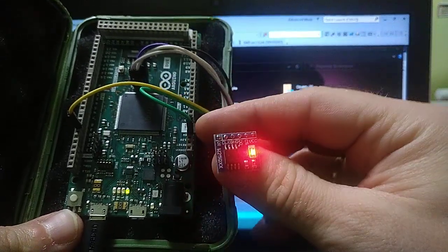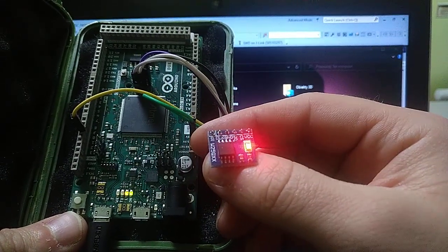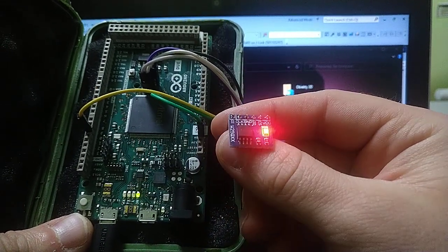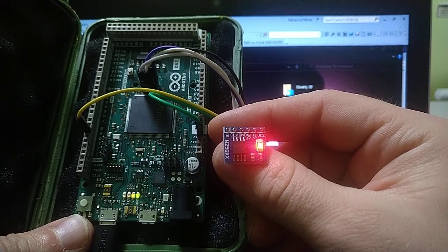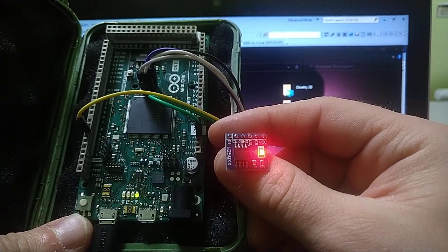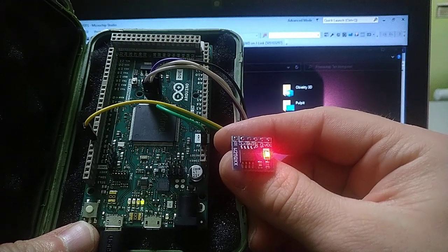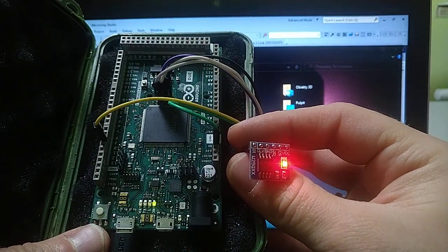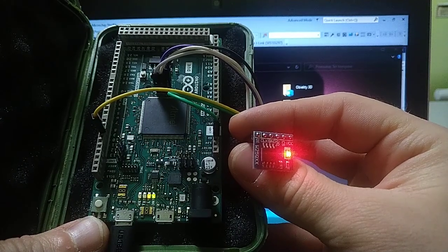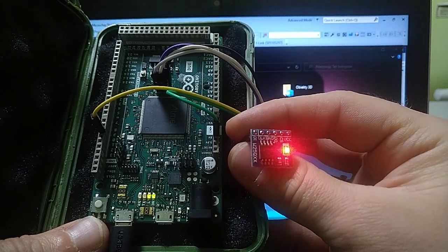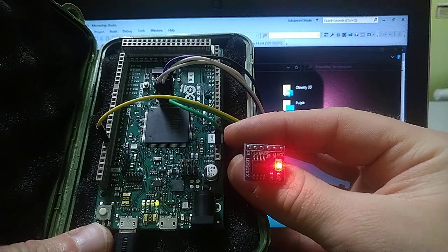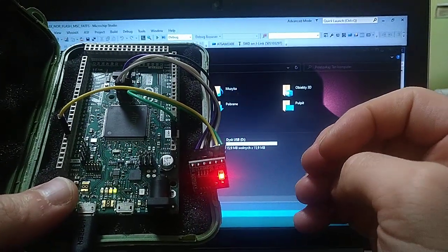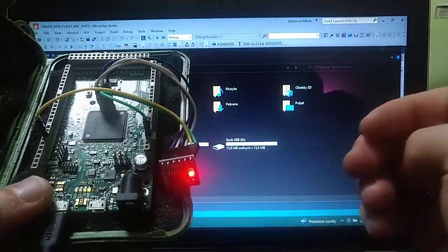In this video we will be using this little guy, which is a NOR flash memory which communicates with the SPI, and we will use it as a USB disk and also as a disk for the microcontroller. So we will use the FatFs together with it to write something to it. And this example writes a test string to the memory on startup.